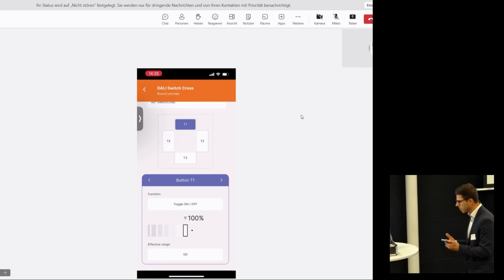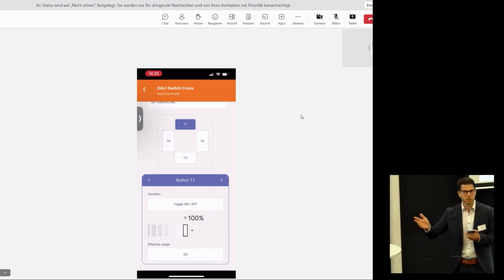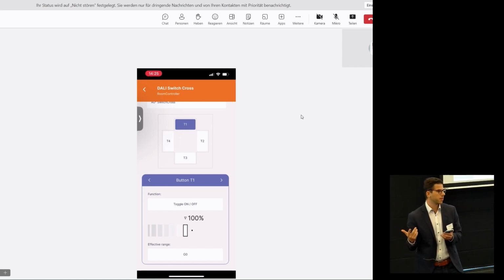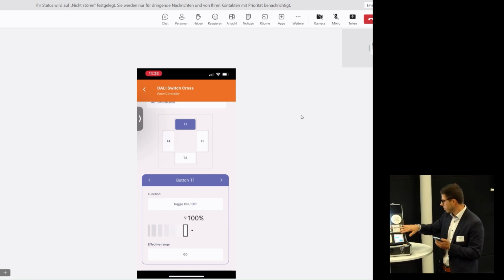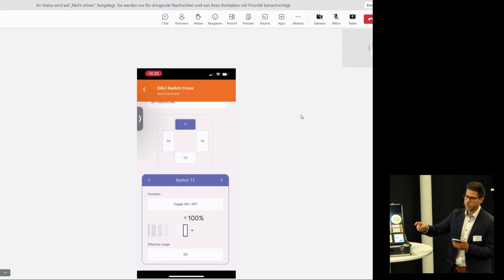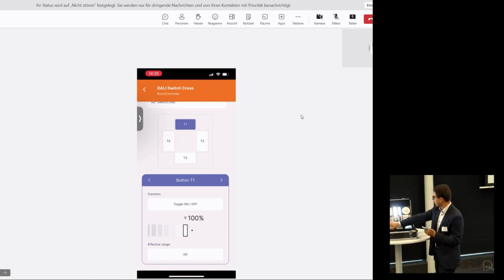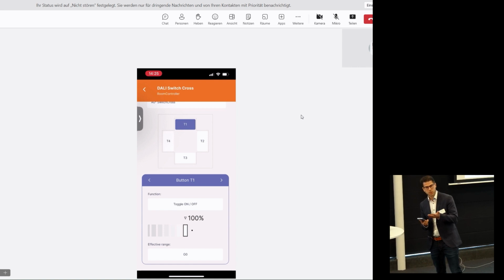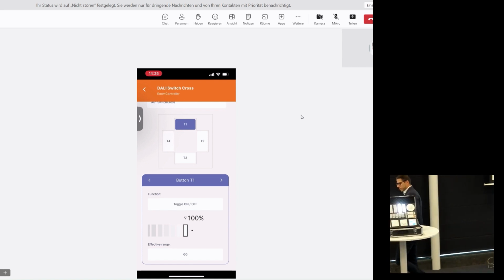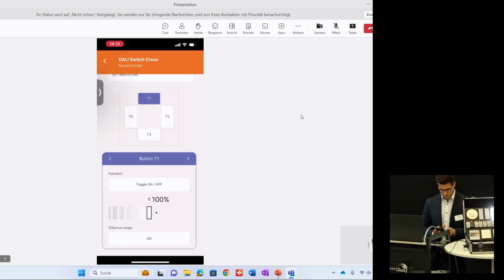So it's just a very neat and easy way to do a small installation. That's also why it's called room controller, and it comes with its own powered DALI line, DALI supply. So there's 200 milliamp of DALI power supply already built in, so you just need that device, and then you can add whatever you want to the DALI line. Also various luminaires. You can use the phone for the configuration and also for controlling the luminaires. So very simple. But now, going back to the presentation, stop sharing.